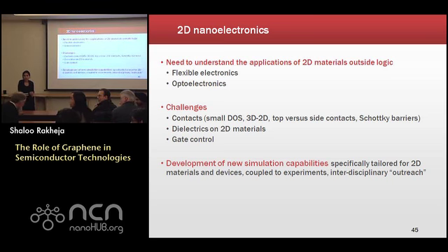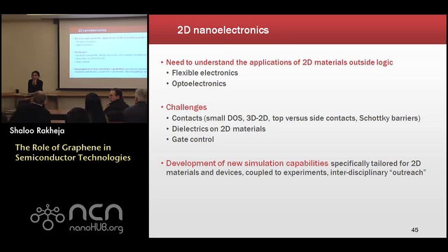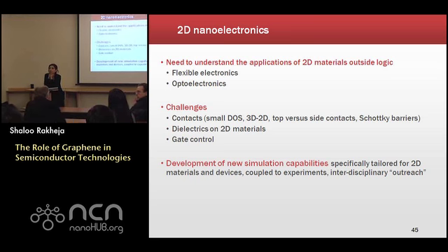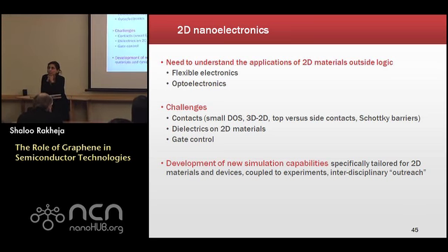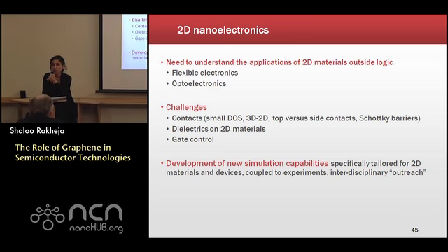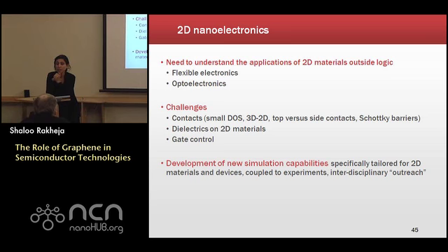From my experience, in the virtual source model the contact resistance is a big parameter, right? You mentioned you got it from measurement. You could get it from measurements. So how you measure for holes and for electrons are different? How you measure? You can't. You can't? I don't think so. You can bias your device either in the electron branch or the hole branch and try to accurately extract your source and drain resistances.